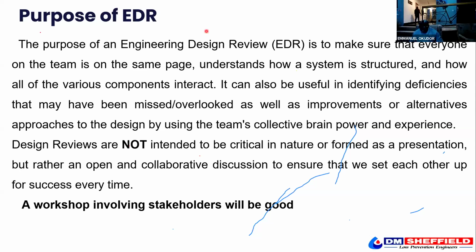And remember, engineering design review is benchmarked to the basis for design. In your basis for design document, you have stated all the code and standard that you have used to design, for example, your relief cases designed to API 520. If you have a flare system, flare stack, depressurization, blowdown, and all that, you have to design to, I think, 520, 521, parts 1 and 2. And we have a series of these codes and standards. So we need to look at them one by one.